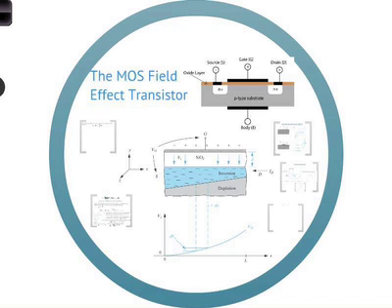Let's review the idea very quickly. The device has a substrate, a source, and a drain, and the source and the substrate are reverse biased under normal operation. The drain and the substrate are also reverse biased under normal operation. If you don't reverse bias them, then you will lose control essentially.